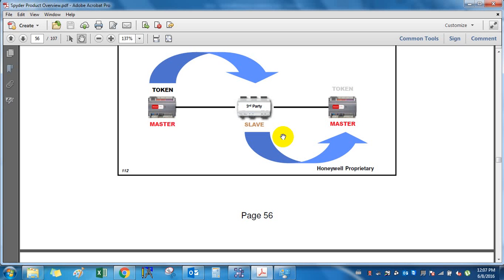This is a 24 VAC transformer. So this is going to your spider. Your spider works from 24 volts. You need to supply that, so for that we have put this transformer. This is 24 volt AC. AC or DC? 24 volt AC/DC. This supports both, but we are using 24 volt AC. So for this controller, AC or DC is okay. This works on 230 volt. This 230 volt, DC? 230 volt AC.